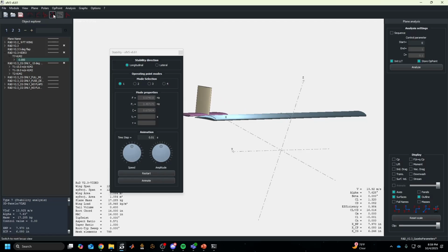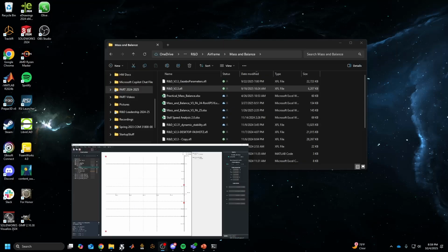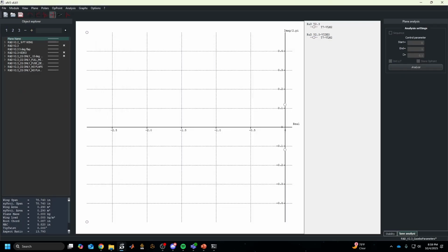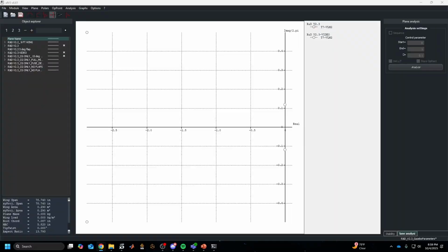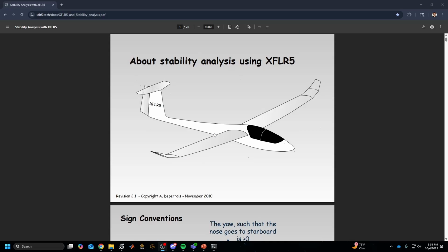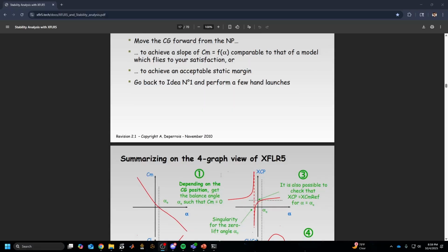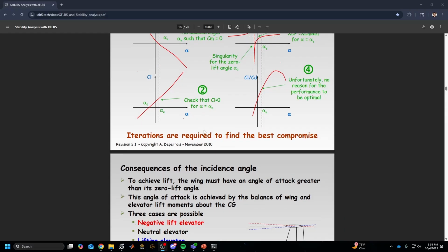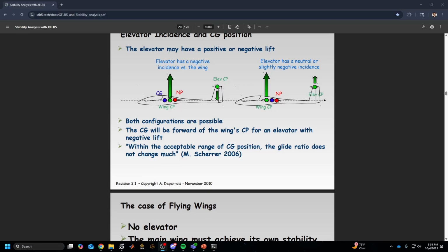All right. If you guys know anything about root locus plots, okay, XFLR put a great document out there for root locus, stability in general. If I can pull that up, where is that guy? Here we go. Okay. So this is their document for that. Okay, it's called Stability Analysis with XFLR5. All right, it's a great source if you want to go through doing all this. Talks about V-tails, how to do that. Talks about all the stuff I've talked about, CM alpha, CL alpha plots, right? Hopefully it agrees with everything I said. Talks about static stability, CG, neutral point, all that stuff.